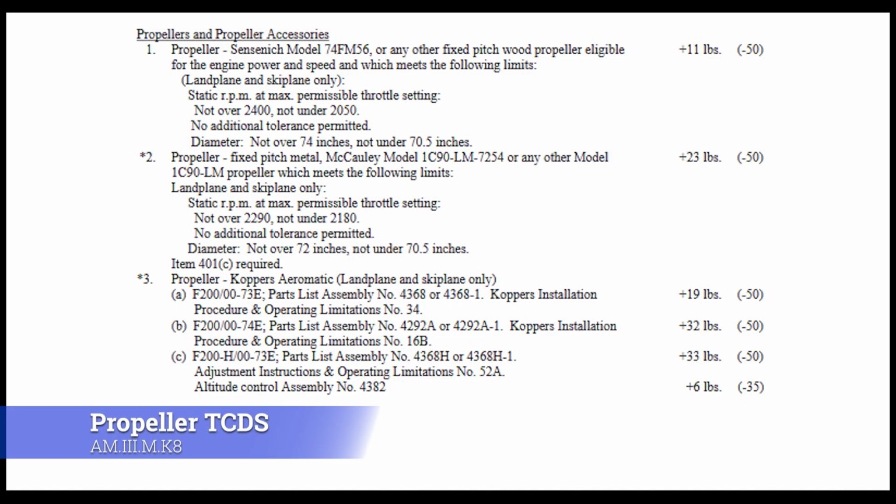And you just check TCDS, and after you kind of get some air under your wings, you start to pick up on it. It's like a lot of them are the same props over and over again. So as long as you see a standard prop, generally speaking, you can rest assured that prop is supposed to go on that engine on that plane. But every once in a while, you'll find some weirdo wacko combination that might throw you off.